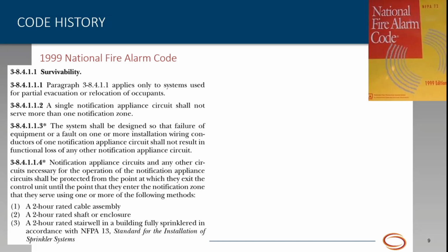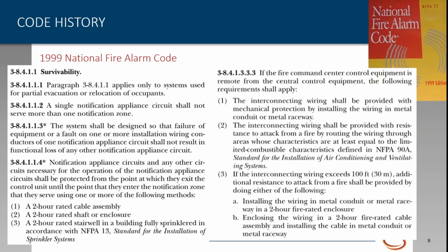This also changed to make, notice it's completely using the term notification appliance circuit. So that's kind of in our normal genre now, rather than just talking about communication circuits. This was important because in 1996, we had the ADA rules that were passed, and it became law that visual circuits and audible circuits need to have the same protection or be valued in the same way. Now, the language about fire command centers, that continued, and again, we'll see how that morphs over time as well.